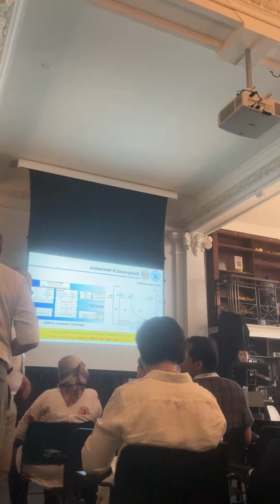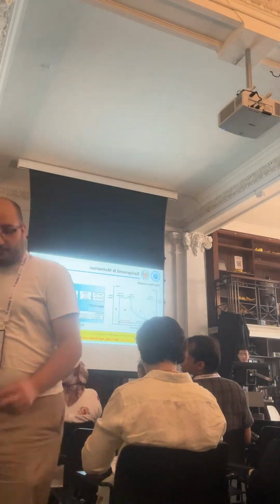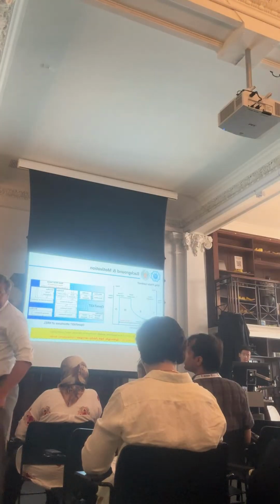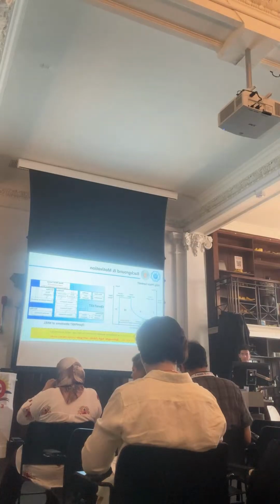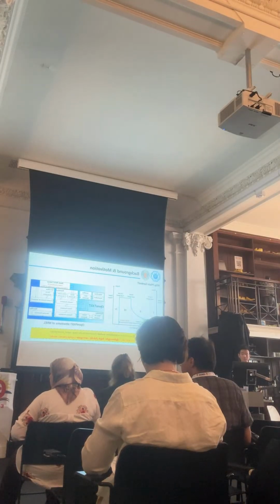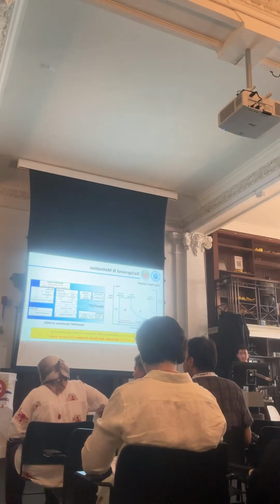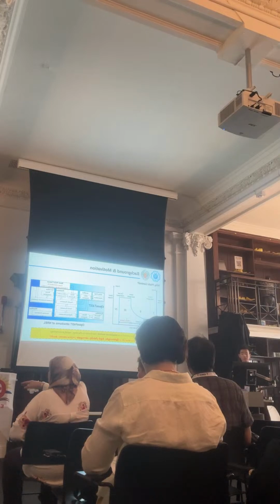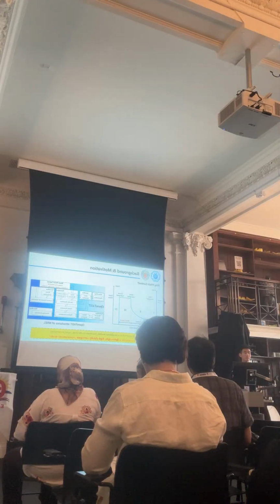As you can see from the wind turbine's power and wind speed curve, between the cut-in wind speed and the rated speed, we just need to use torque control to capture the maximum power output. But when the wind speed exceeds the rated wind speed, we have to use pitch control to adjust the blade pitch angle to limit the power output to the rated power. It can also help to reduce the structural loads on the wind turbines.